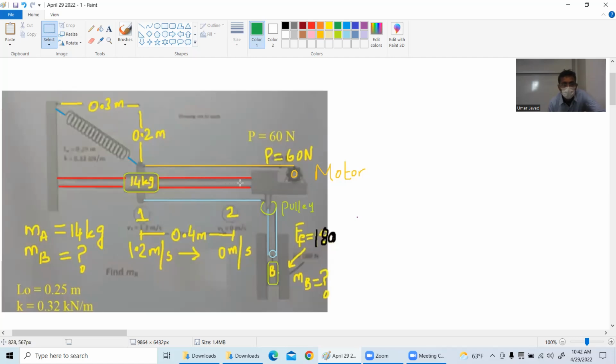And when eventually it arrives right at this point, it automatically should stop, because of the spring force, along with the counterbalance, along with the fact that when this weight moves up or down, there is a friction force of 180 Newton because of the walls as well. So everything combines together. You switch on the motor, and eventually the velocity goes to zero right when the 14 kilogram, the fellow that holds the gate, arrives.